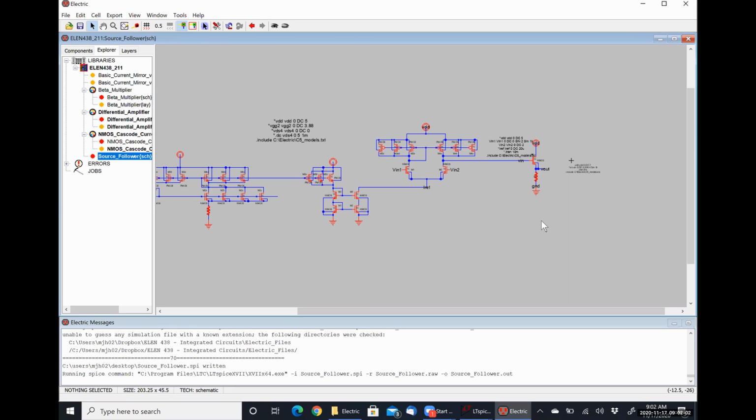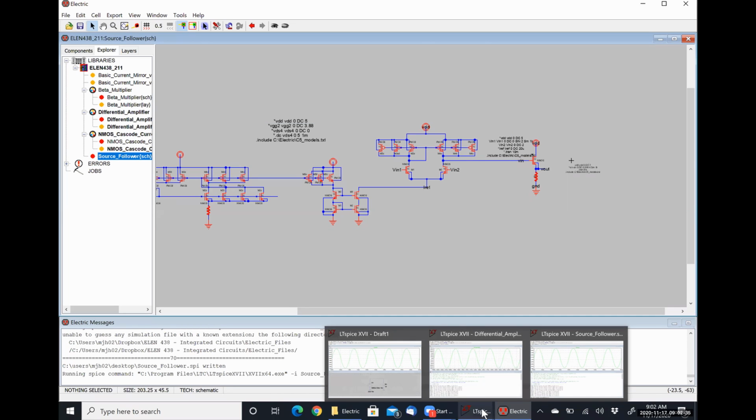Just a little tidbit, not that it's super helpful now, but just remember that you can divide the voltages in SPICE to find the gain. You can just add a trace and divide the voltages that you want. I'm not sure that I follow. So we were actually just mathematically finding the gain by division, right? Oh yeah, that never even crossed my mind. Yeah, you can do the math.